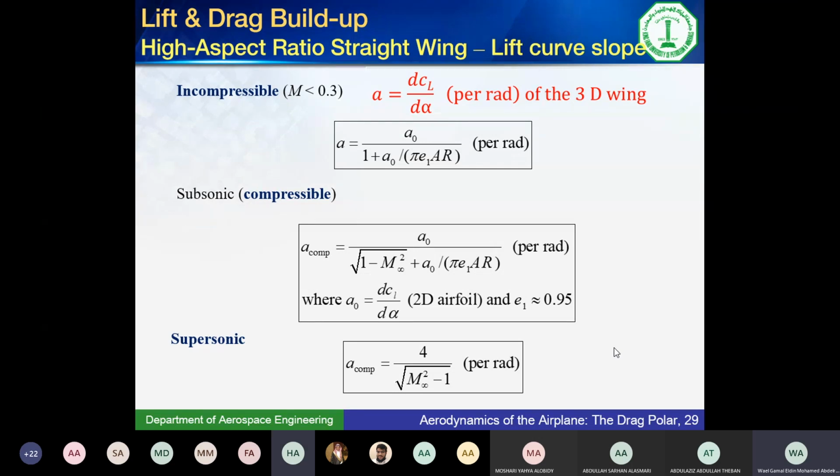An airfoil is essentially a wing with an aspect ratio of infinity, right? The span is infinity. As the wings get shorter, they get less aerodynamically efficient. So the equation that we have here says as aspect ratio decreases, that means the span of the wing decreases, then A will decrease, because this is on the denominator. It's on the top. So this one will decrease from the 6.2.